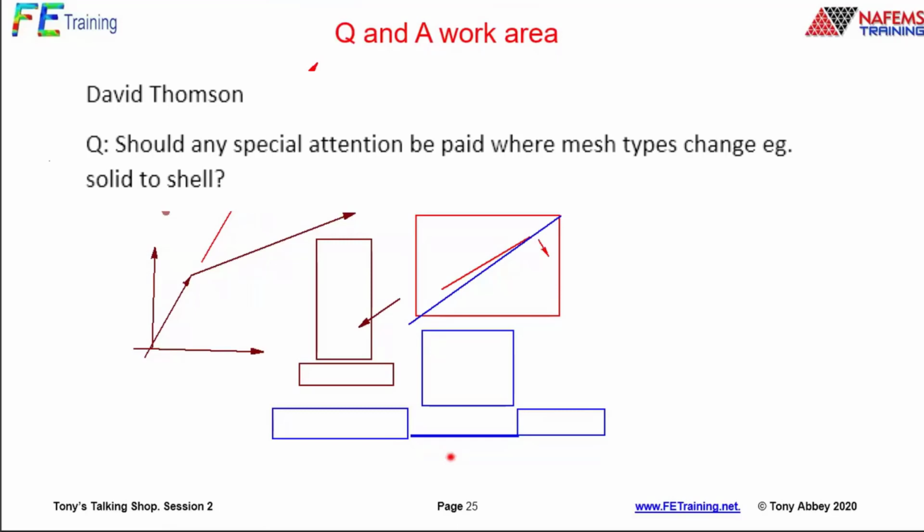Just a quick aside, when I worked on the help desk at a couple of companies, we had a short checklist for when clients sent models in saying something had gone wrong with the model. Top of our list was, are we using dissimilar elements in this model? If we're using dissimilar elements, we go look for issues like that. So that's a very good point there, David.